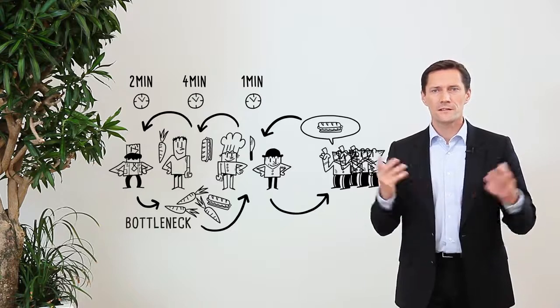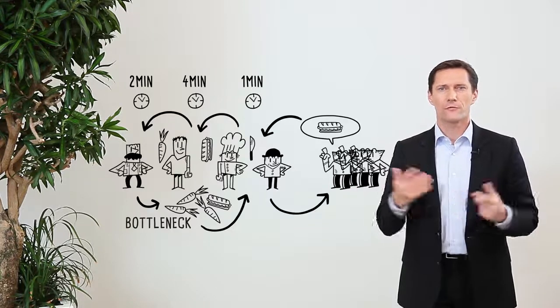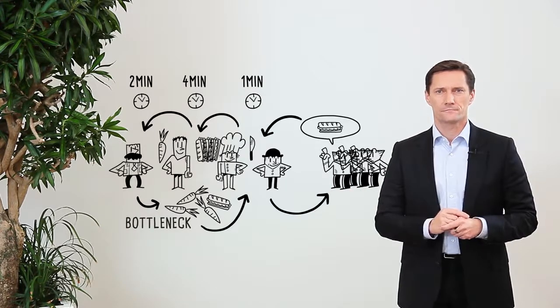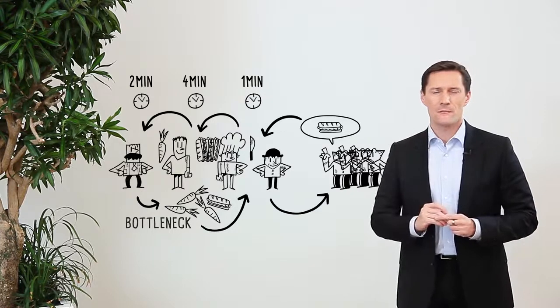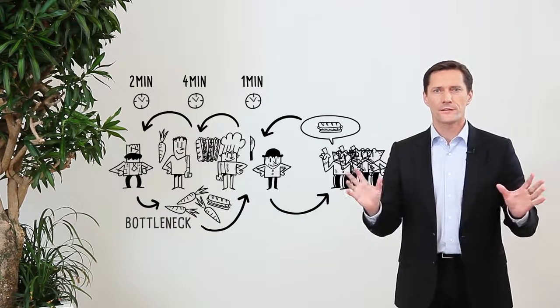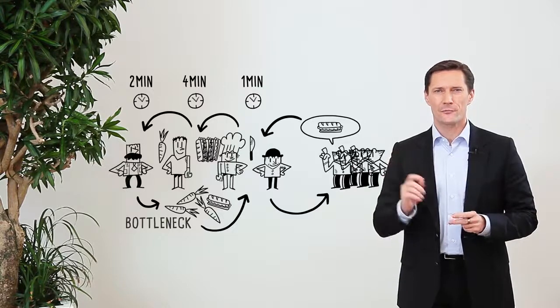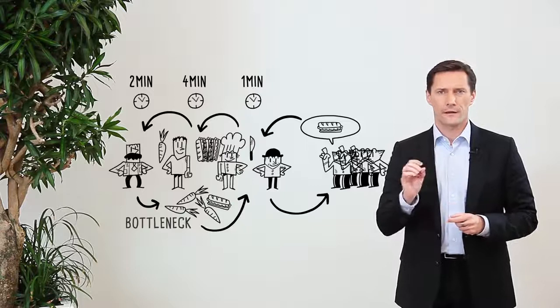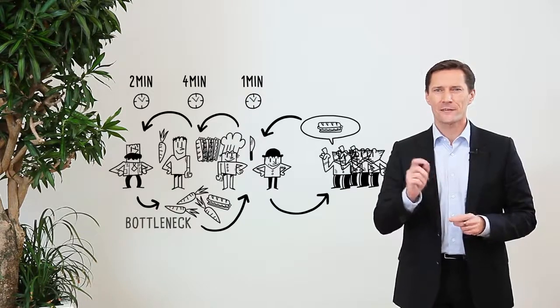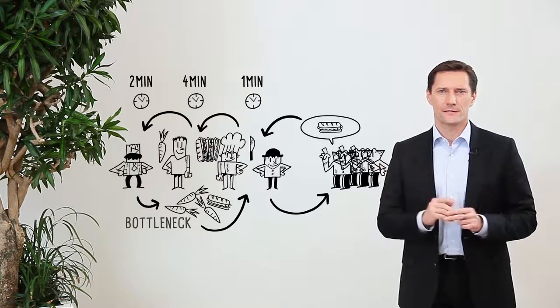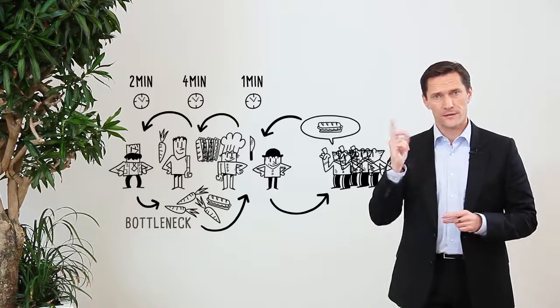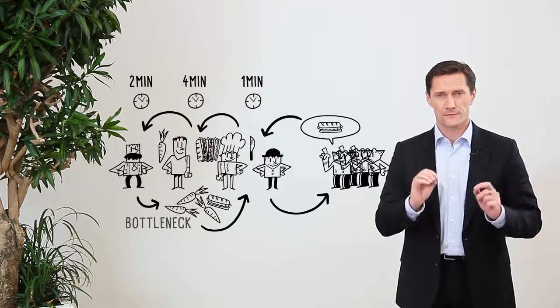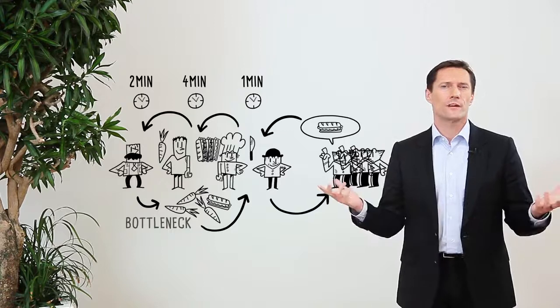In addition to that, in front of B, you will find a lot of sandwiches waiting. But that's something we need to remember anyhow. Whenever you see a lot of inventory in front of a process compared to the others, it's a typical sign for a bottleneck. It is obvious that a redesign is needed. So important, remember the takt time. We need 2 minutes. So what do we do now?